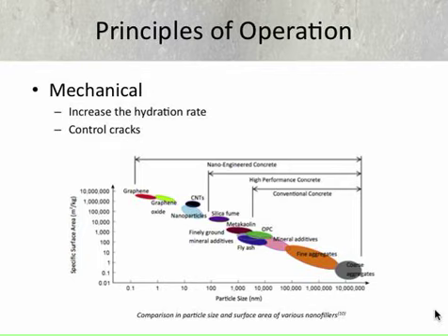So regarding the mechanical properties, the major principle that nanoparticles introduce is the control of the hydration rate. Since the spacing between the individual particles is so tiny, they are distributed at a finer scale as compared to, for example, traditional fibers. In the past, cement powder was deemed to be the finest component of binding aggregates to form conventional concrete. And if we look at the figure, we can see that the particle size is greater and surface area is much less than that of the engineered concrete.